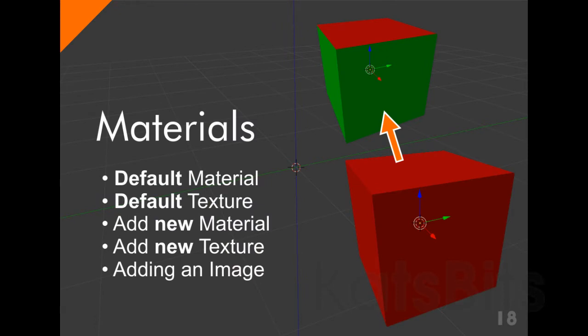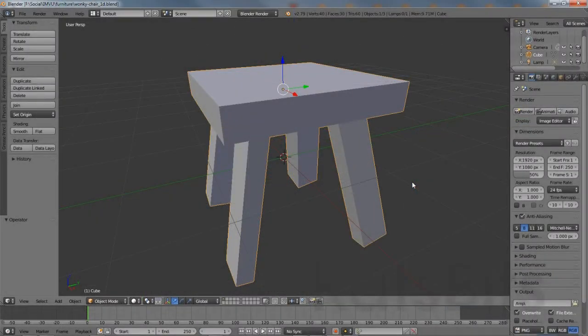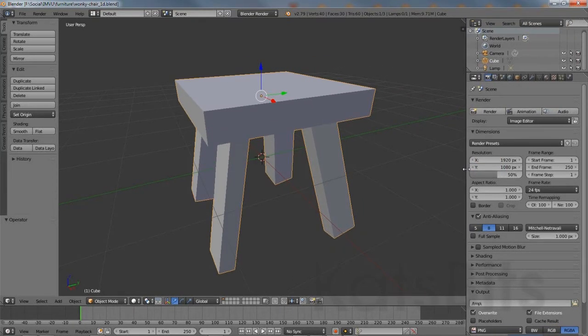The next step after the mesh is made is Materials, either editing the pre-assigned default or adding a new one. First, editing a pre-assigned material. Before editing materials, move the cursor over the border between the 3D View and Properties section, left-click drag to expand when the double-headed arrow appears.